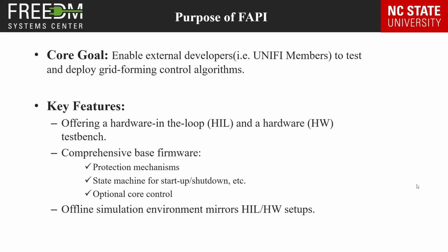The FAPI framework provides the external developers, that is the UNIFI members, the opportunity to implement and evaluate custom controllers without needing to concern with lower-level firmware. The core goal of this framework is to enable external developers to test and deploy their grid forming control algorithms. The key feature is to provide a framework for GFM controls validation that is compatible with the NCSU Typhoon hardware in the loop setup and multi-inverter hardware testbed.